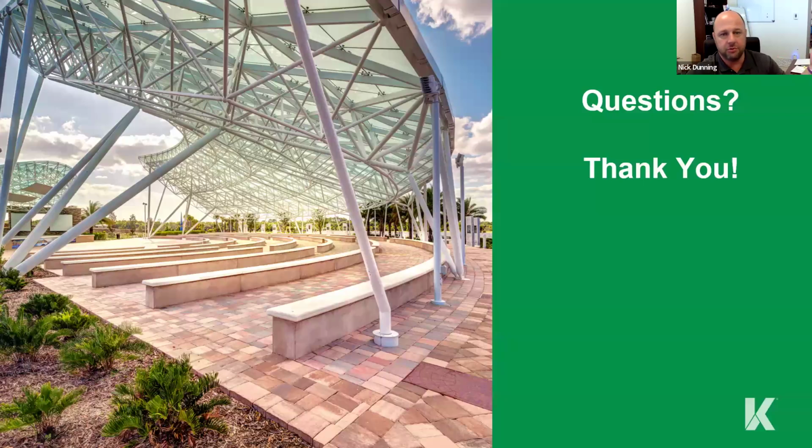Now, if you have gable ends and you put in what's called let-in bracing, which is like cross bracing, a lot of times that'll work. But we've unfortunately been brought into projects after the fact and have to inform the clients that we're going to have to take everything off and reinstall it, because right now the building is lacking in shear reinforcement, so we could have an issue in a storm. A lot of people say, "Oh, it's siding for siding, I don't have an issue with it." You have to understand what's going back and what the limitations are, and that's another reason a third party can help you out by saying, "Look, this needs to be done," or maybe don't use this product because you have to do the extra work. So always consider the whole system.